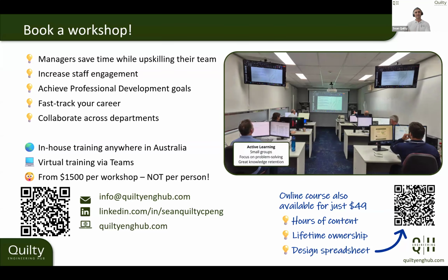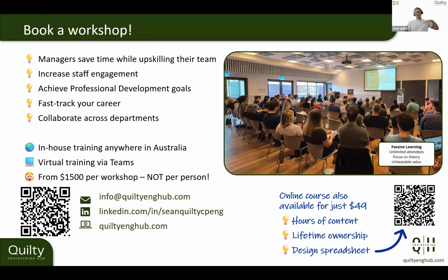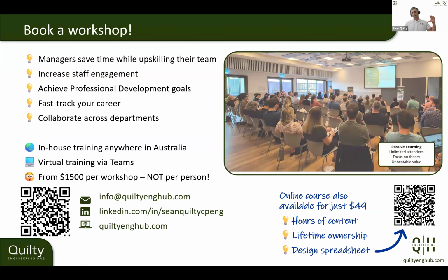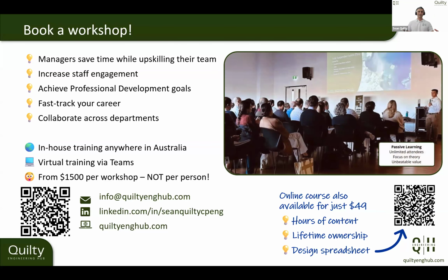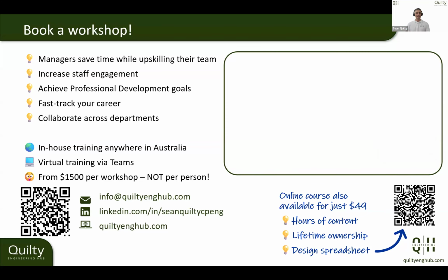And the reason why we use the DV values rather than just a maximum depth is you could have, say, over a meter high of water, but if it's traveling super, super slow and someone got stuck in there, they can kind of wade their way out and it's not that dangerous.